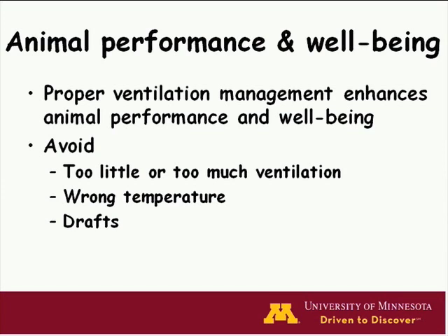So practices that conserve fossil fuels but reduce feed efficiency or rates of gain are not going to be acceptable by producers. So we need to avoid excessive ventilation, and we also need to avoid having too little ventilation, or we need to watch out for having the building at the wrong temperature, either too cold or too warm, and we need to avoid creating drafts with the system.